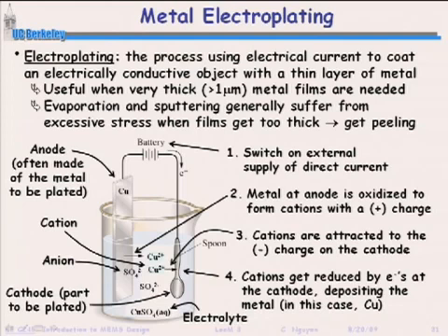The way this works is you put a battery between these two, and the battery will suck away electrons from the copper. If you have this copper sulfate solution here, copper ions will go into solution, and because of the electric field across these two, they will travel from the anode to the cathode here. Once they get to the cathode, they'll recombine with the electron, which means they deposit onto that spoon. So it seems like a very, very simple process, and it is very simple in your high school lab class, right? Because you'll grow a film over that spoon.